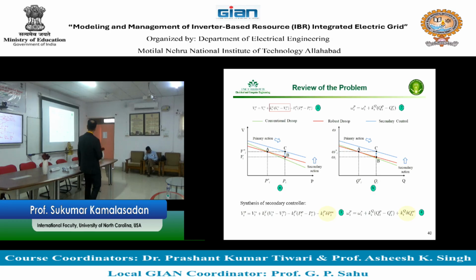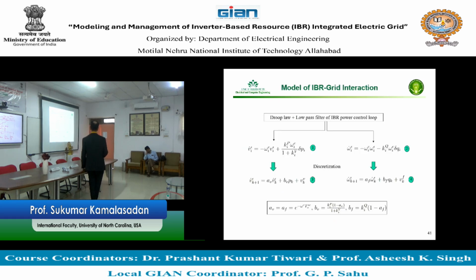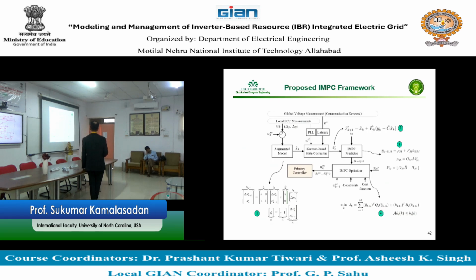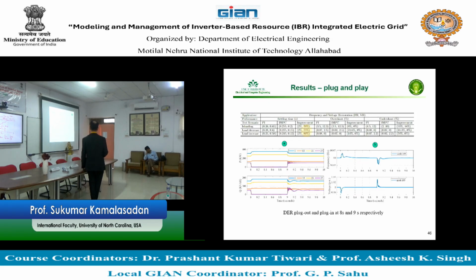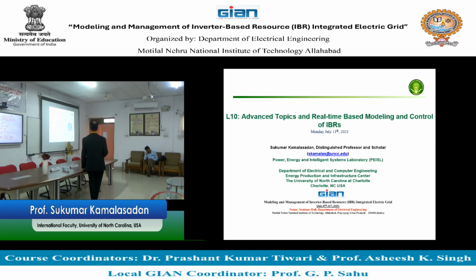So in here, what I'm talking about is PV droop. You see, when the power pushes from here to here, the voltage goes down. You have to lift that voltage. That is done by the secondary action, or secondary control action. So you have an integral term that goes into the secondary control action, and you can actually control the output. So maybe I'll stop right here.